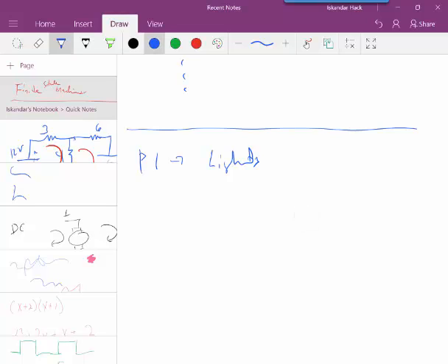So we've got our right turn sensor. And again, the project will be toned down if I decide to use this for the project. Our push button. So whenever I simply do that, first off, the way that you're going to encode this is you're going to set up an enum, an enumerated type, and you're going to call it states, and then you're going to list all the possible states.